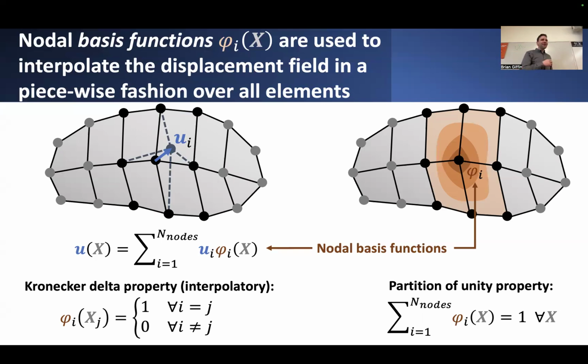So, much the same way as we might proceed in any Galerkin method, we suppose that the solution, U, or rather an approximate solution that we will seek, can be represented as some linear combination of these so-called basis functions. These basis functions are really nothing more than, in the case of finite elements, these interpolating functions, which individually multiply some set of displacement coefficients, which in the finite element context have the interpretation as being the discrete values of the displacement at particular nodal points.